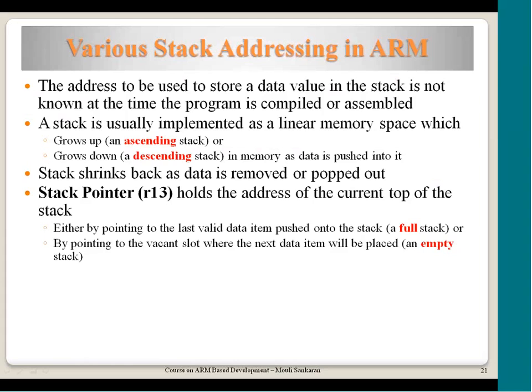Both options are available in ARM, though some processors implement it in hardware and support only one. One good example is the x86 family, where the stack always goes towards lower memory, and it is specific to the hardware implementation of the processor.